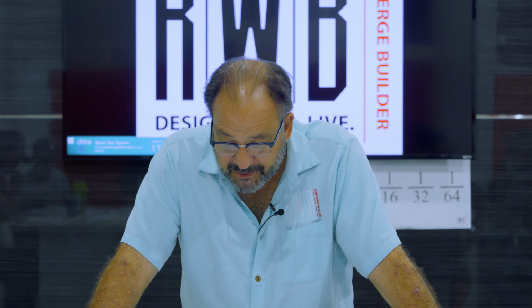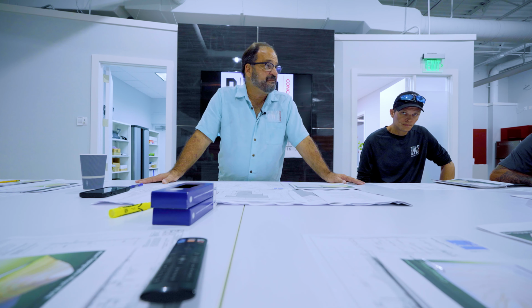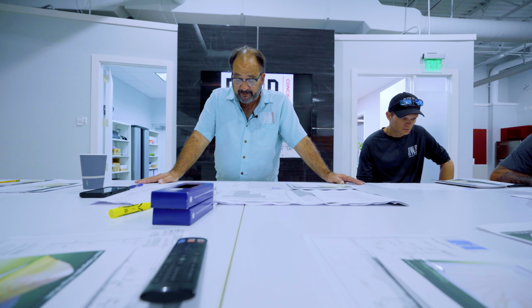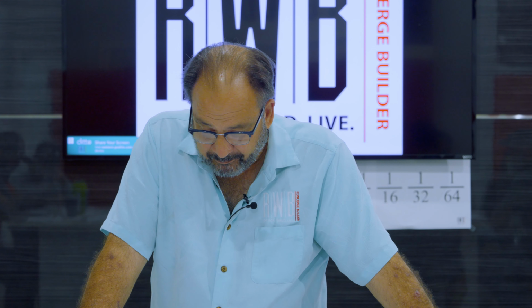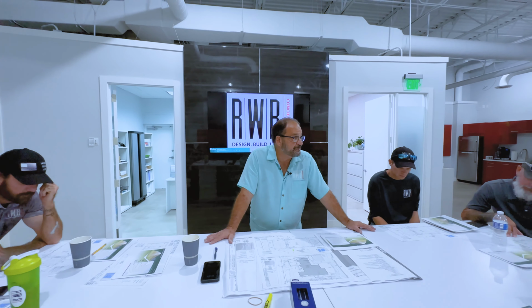Okay? Certain things, for example, when you get to the east side of the street, certain surveys are required to move forward with DEP. For example, if you're going to file a DEP permit for anything on the east side of the CCL, and I'll explain that in a second, you need a survey no older than 6 months old. So if this, mainly to establish the mean high water line, but if you had this and it was a year old and you went to the DEP, they would not accept it.